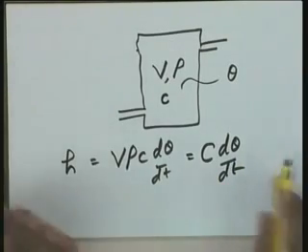With these two, please note, in thermal systems there is no parameter identical or equivalent to inductance. So, we will have resistance capacitance circuits only whenever I write dynamical equations for a thermal system, and the example of the thermal system I will take in the next class. Thank you.